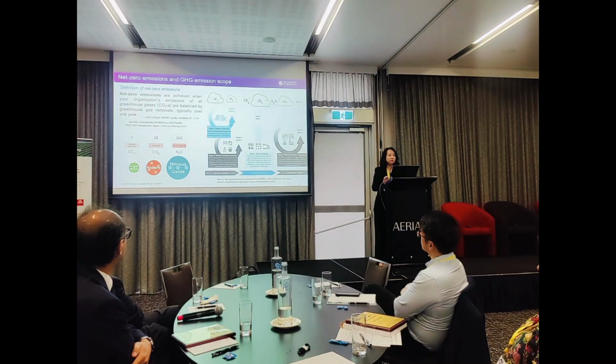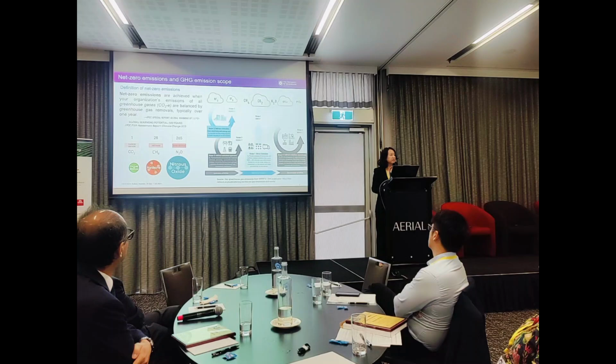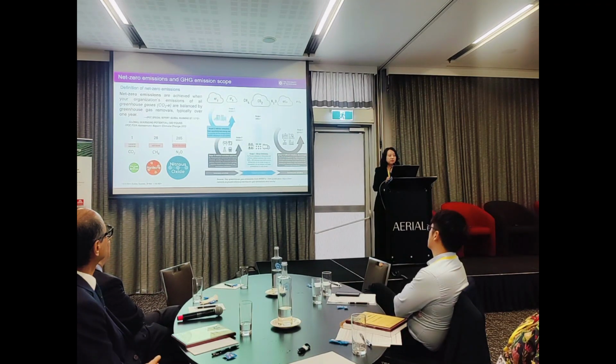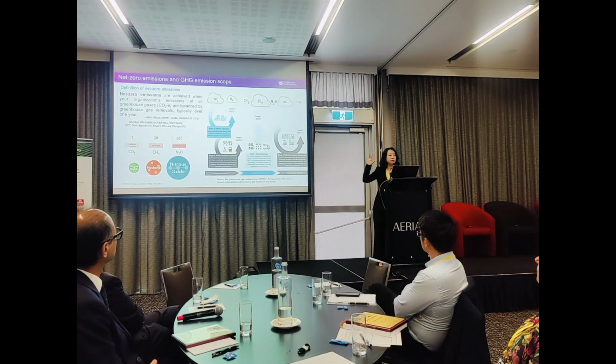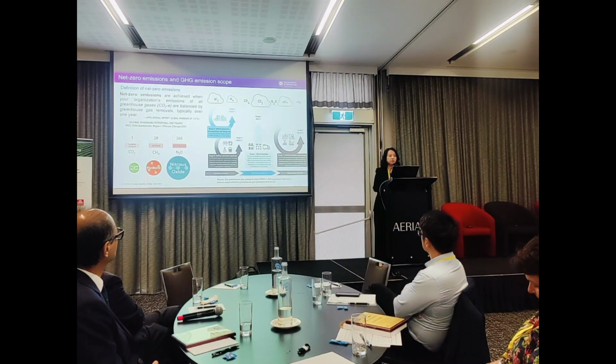In the water industry, we are normally obligated to report two scopes. There are three in total, but we are obligated to report Scope 1 and Scope 2. Scope 1 is the direct emissions generated during the process, including some fossil CO2, methane, and nitrous oxide. Scope 2 is indirect emissions, related to energy consumption generated from fossil carbon. Scope 3 is not obligatory for water utilities to report, but it relates to the supply chain: the upstream chemicals we use, and if we build a new plant, the cement we use, which is embedded carbon. Downstream, if solids we generate are applied to agriculture, the additional emissions from those are also Scope 3.